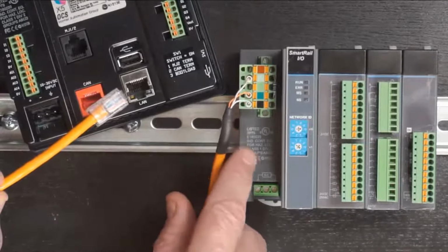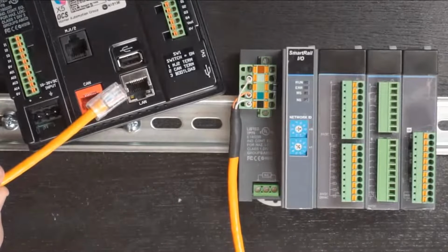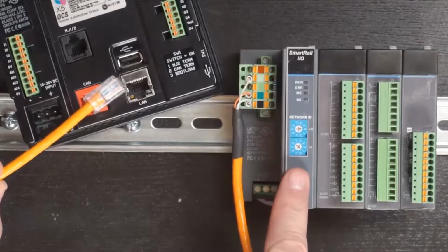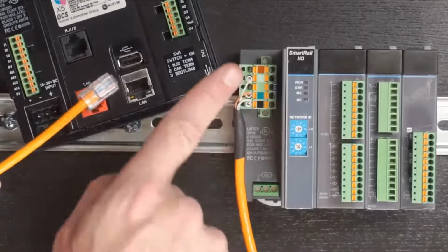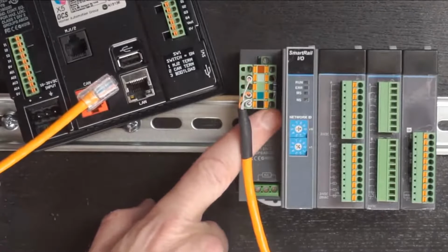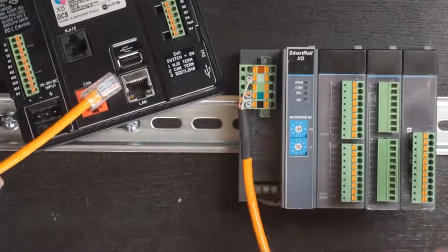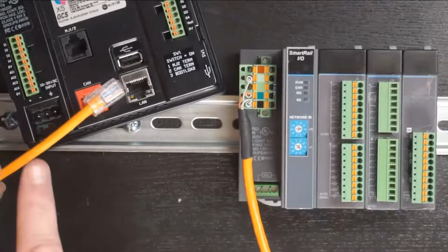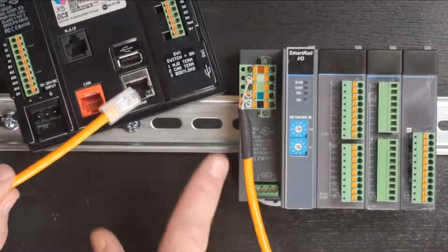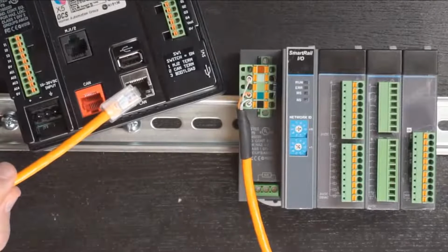Okay, and just like I told you a minute ago, this cable as of yet has not added 24 volts DC to the SmartRail. So in this case, I would go ahead and land the plus 24 volt conductor here and the common conductor here running to a 24 volt DC power supply to power the SmartRail base. You wouldn't run 24 volt DC power in most cases over Cat 5. You'd use discrete wiring connected in through the plug. And the double plug, again, nice and convenient.